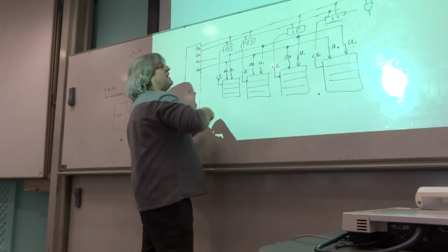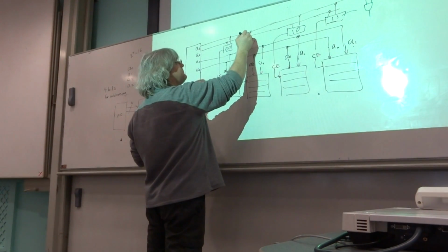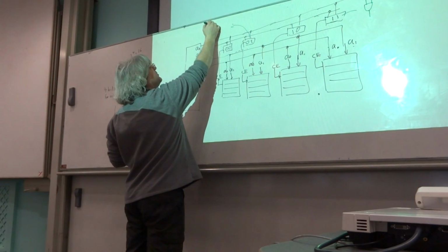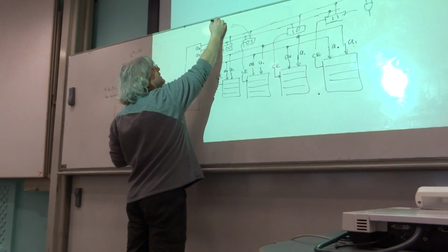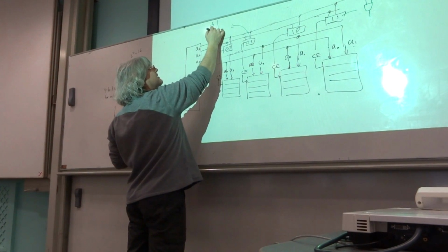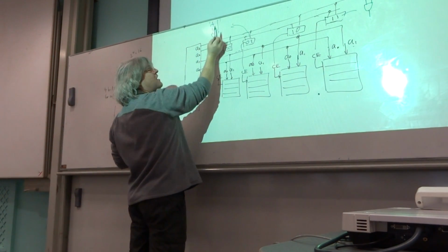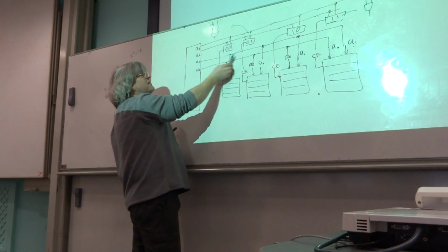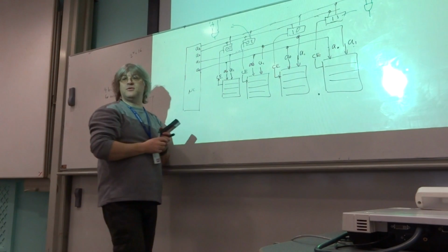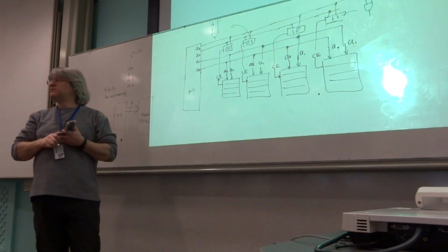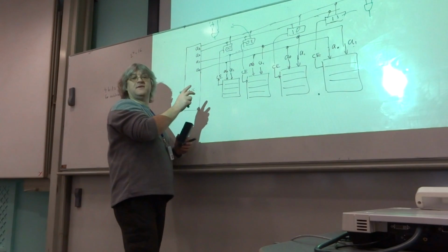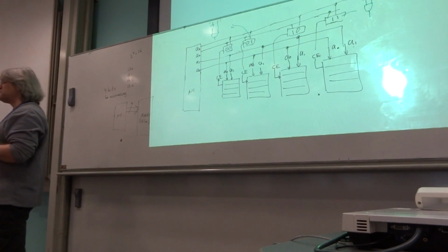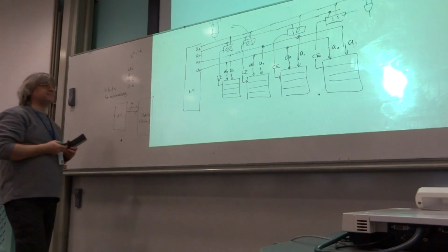Now, if you want to know how to do it, let's say we do this one. So that's a 0 and a 1. What I could do there is put an inverter here, and then this one coming in here, and then my AND gate again. So now, when this goes low and this goes high, low becomes a high and a high goes high, which switches this on, for example. So address decoding in itself generally doesn't require too much in the way of complex logic gates, but they have to be carefully chosen.